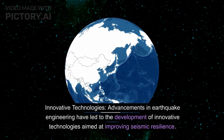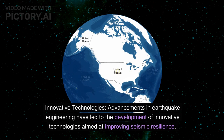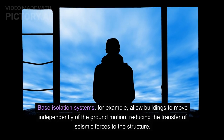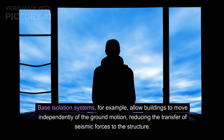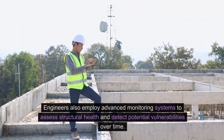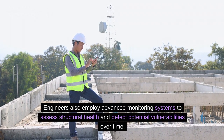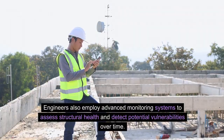Innovative technologies. Advancements in earthquake engineering have led to the development of innovative technologies aimed at improving seismic resilience. Base isolation systems, for example, allow buildings to move independently of the ground motion, reducing the transfer of seismic forces to the structure. Engineers also employ advanced monitoring systems to assess structural health and detect potential vulnerabilities over time.